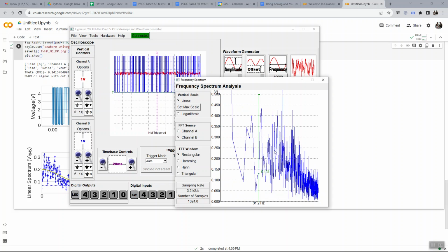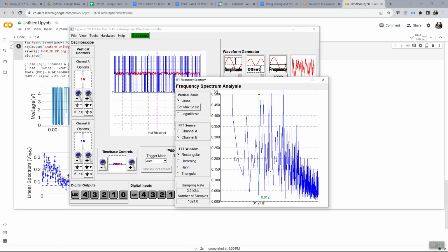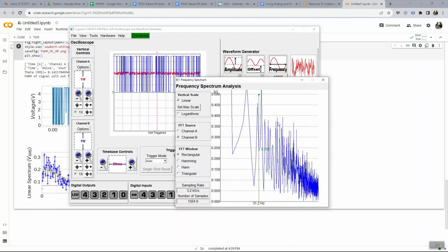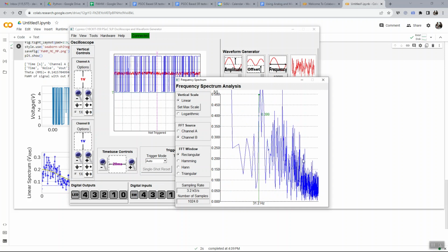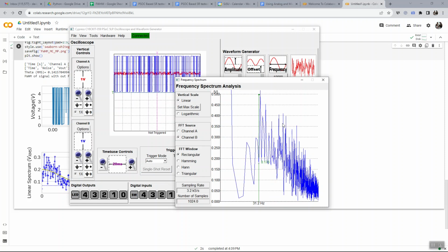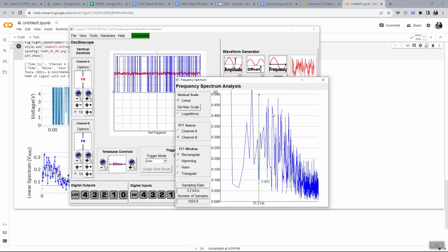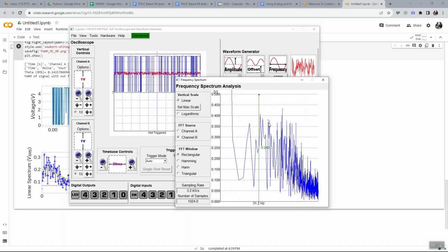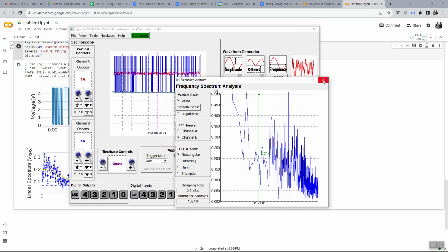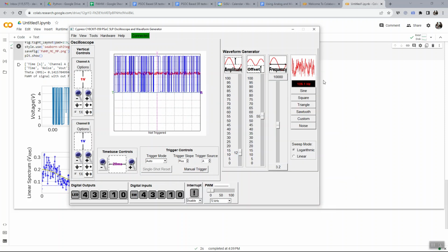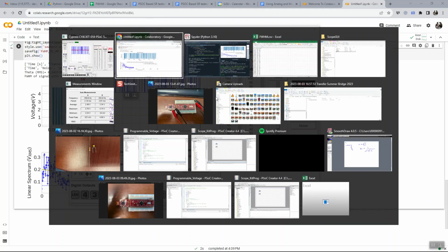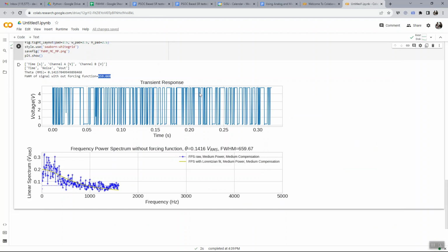All right. And you can see this is the noise, and it has a kind of a peak in frequency, or peak in magnitude, and then it rolls off, right? But these spikes are all over the place. So what we do is we take the power spectrum density, which really is based on the FFT, right?